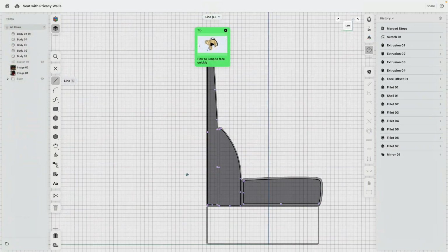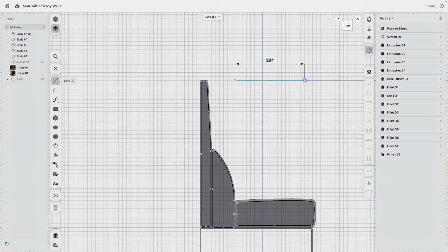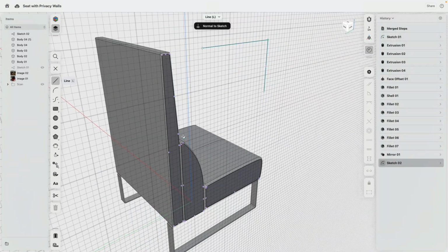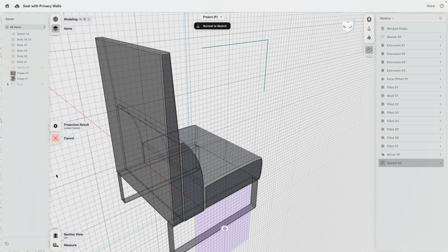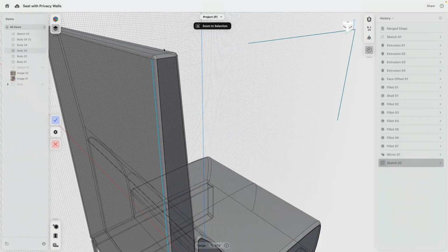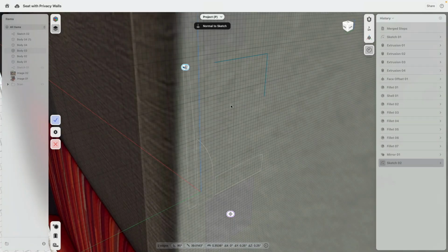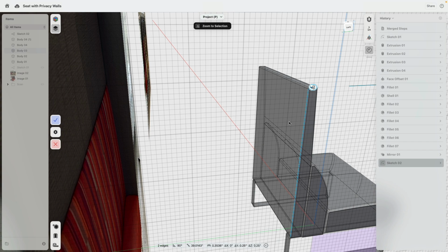Okay, very good. And now we need to know, when I draw here two lines, where would the left and the right edge be? Now I could draw this by hand, but I want to be very precise. So I'm projecting edges into my design. I go to project and I have, for example, here one line and I have there one line. Sorry, there's that image in my view.